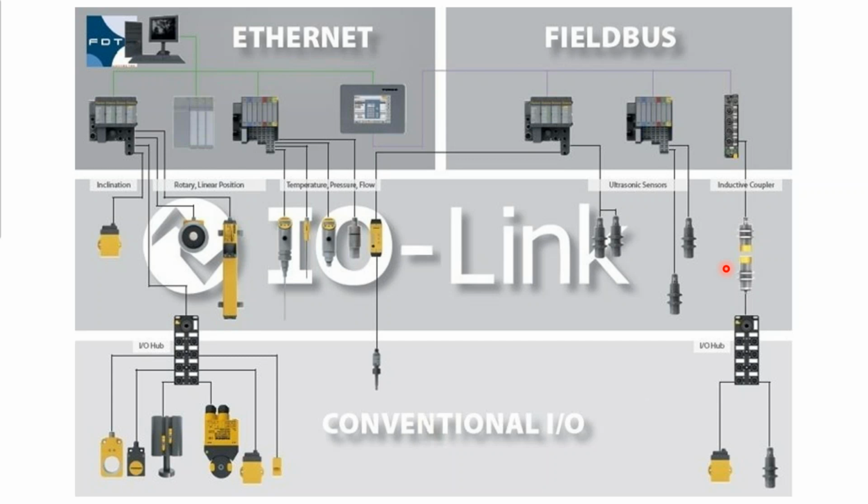And then some devices, you just still have to have good old I/O. So whether it's a push button or a simple sensor, this device here and this one here, these are I/O link hubs. So just like your old multi-port with a multi-pin home run cable junction box, this is the same type of thing, but for I/O link, and we'll talk more about that. But now you can put discrete on-off signals onto the I/O link network as well for your application.